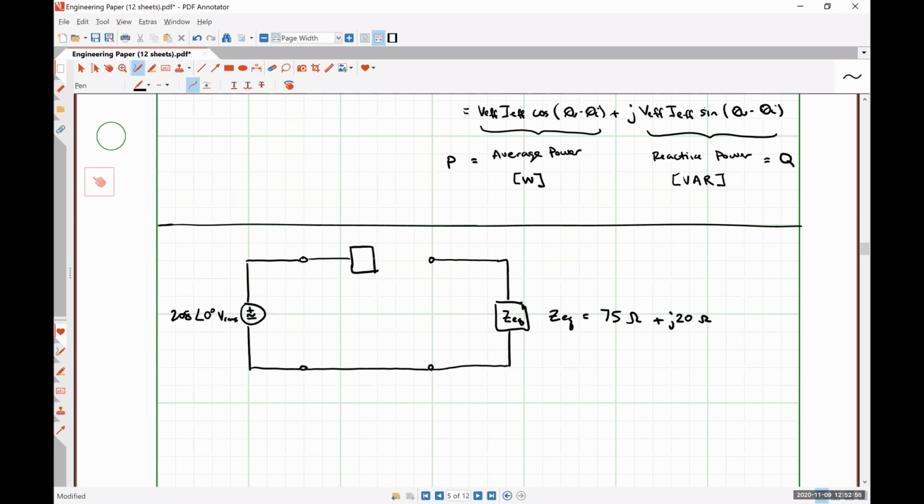the voltage present at the transformer to the loads presented by the house are transmission lines, right? You can look outside and see several of them. And we're going to say that this line has very low losses. So let's call it on the order of 0.3 plus j0.1 ohms for our losses.